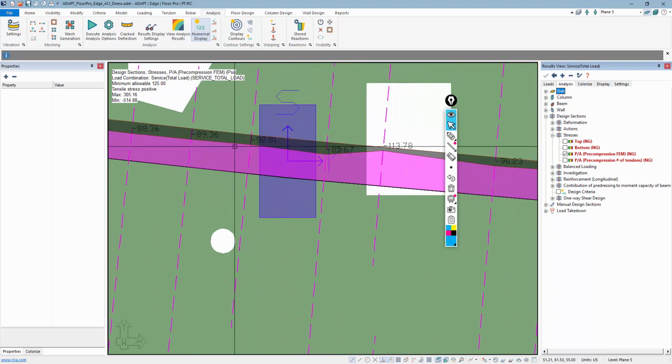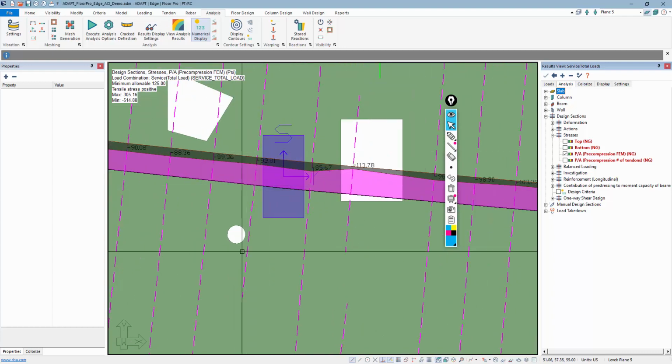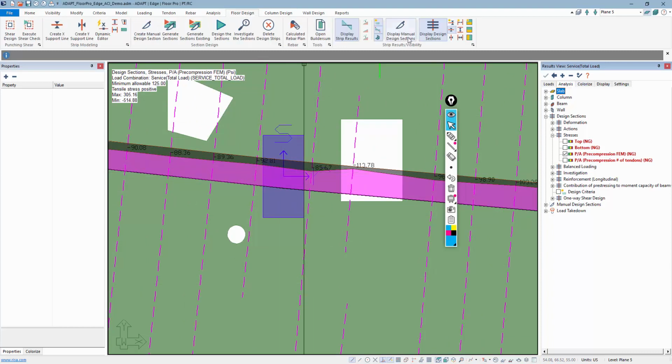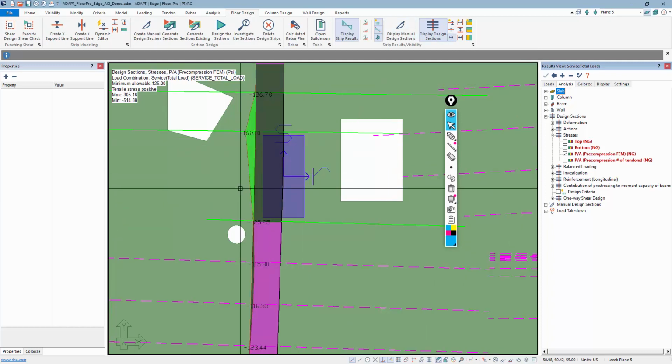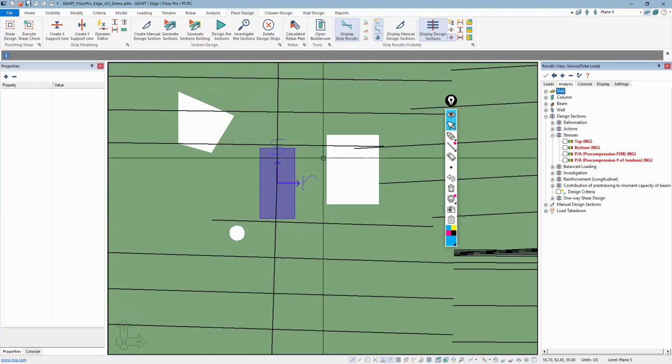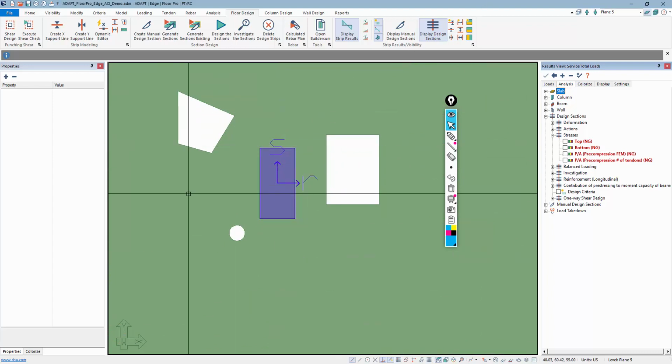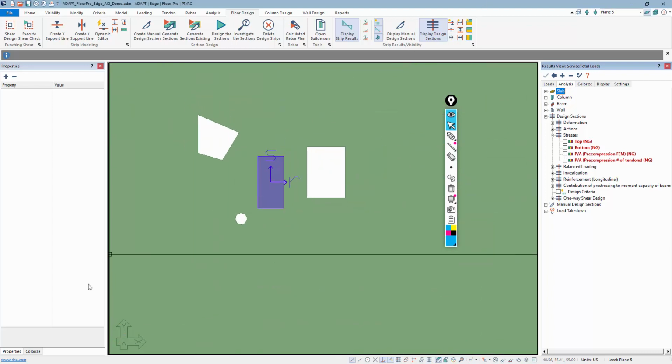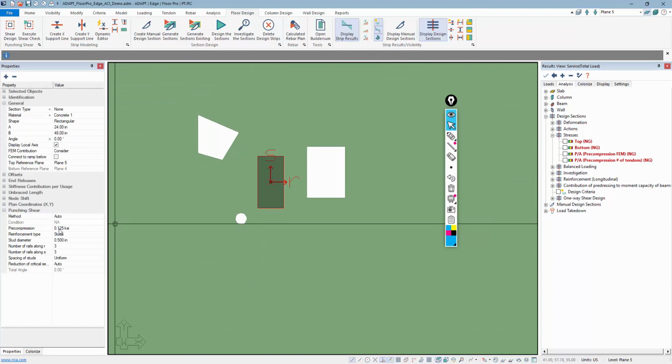That means we're taking the axial stress that's integrated on that line over the area of the cut. So this is 92 and 85, and then in the other direction, if I just toggle this to the Y direction strips, I get 168, 125. So the user can make some judgment as to what value to use for that pre-compression input aside from just using the default 125. So that's what that's for.